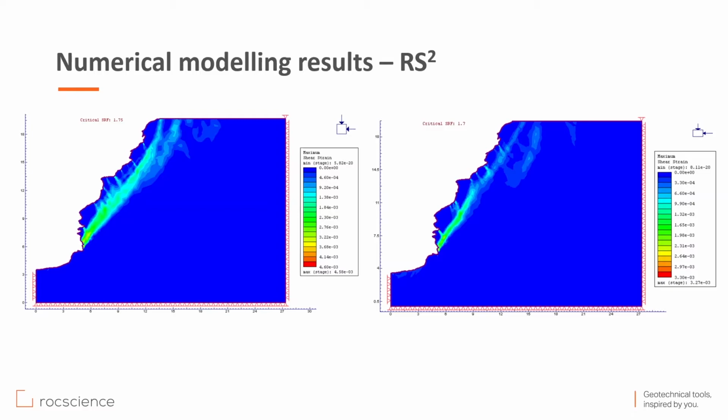With Eurocode 7, partial factors of safety are applied to different components of the analysis. The partial factors are applied prior to the analysis to give design values. The final result is an over-design factor which must be greater than 1 to ensure the serviceability limit state requirement is satisfied in this case.